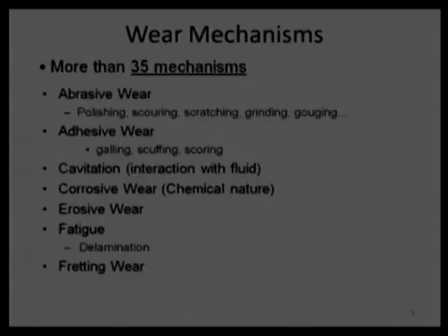We are talking about micro motions which are induced with the vibration. Even though there is no relative velocity, but there is a micro motion, there is a micro slip phenomena happening. It will again and again knock the surface and will cause some failure, some removal of material, and even the particles which are getting removed from the surface, those will increase this kind of wear. So, we generally avoid it if we understand all these mechanisms.